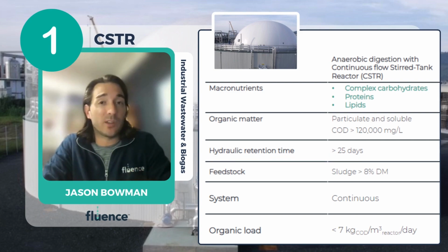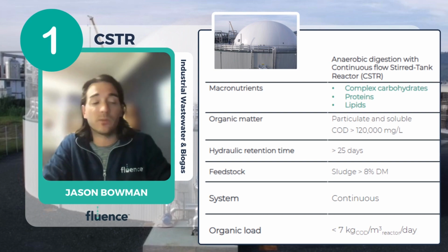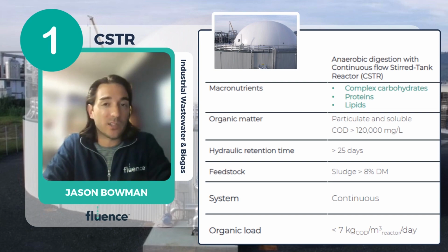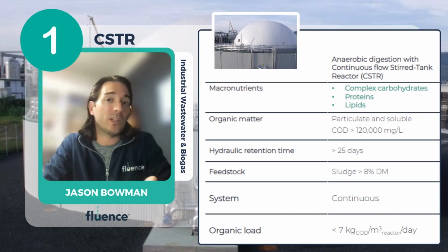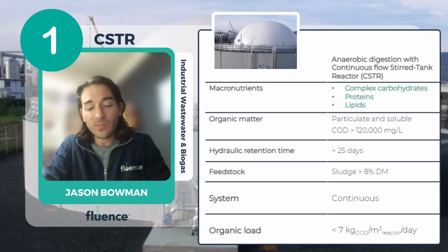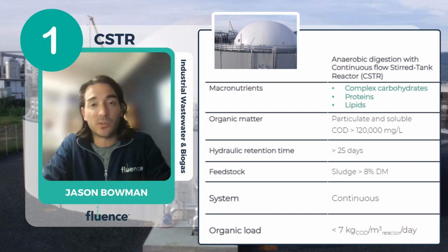As I said, these systems are very simple. This is because they do not operate with an external sludge recirculation. So what comes in is essentially what goes out. In other words, for every gallon that comes into the tank, 1 gallon is going to exit the tank. Again, very simple. This is what's known as a complete mix process, where in theory, every point inside of the tank has the same concentration. The issue here is that we need a high hydraulic retention time because we have to have a high solids retention time. Since there is no external sludge recirculation, the hydraulic retention time and the solids retention time are the same in this case.